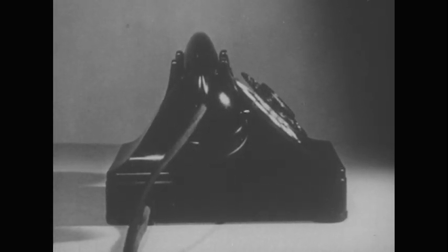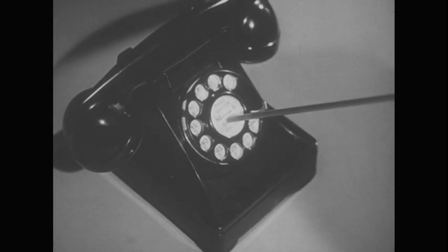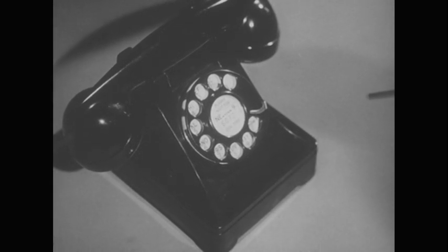In order to see the dial in its true shape, you have to look at it differently. That is, you need a view made out here, as if you were looking at it from this direction. Since this view would not be the same as any of the principal views, it is called an auxiliary view. An auxiliary view will show the dial in its true shape. If you study the relationship of the projection planes, you will find auxiliary views easy to understand.